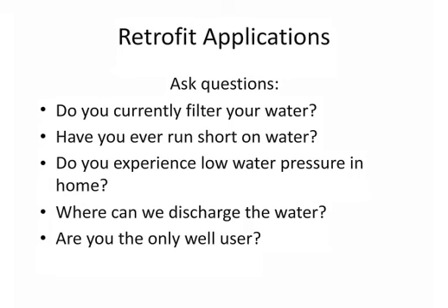And I always listen intently to that response, because it'll give you indications whether you have a viable candidate, because you don't want to have to do a lot of filtering to provide the water to your heat pump, because those maintenance costs, number one, over time will get neglected, or number two, could start to take away from the savings of that heat pump and make your customer less than happy about their installation.